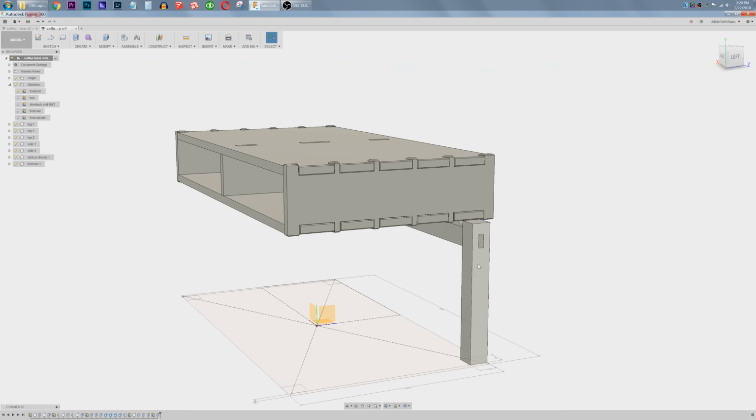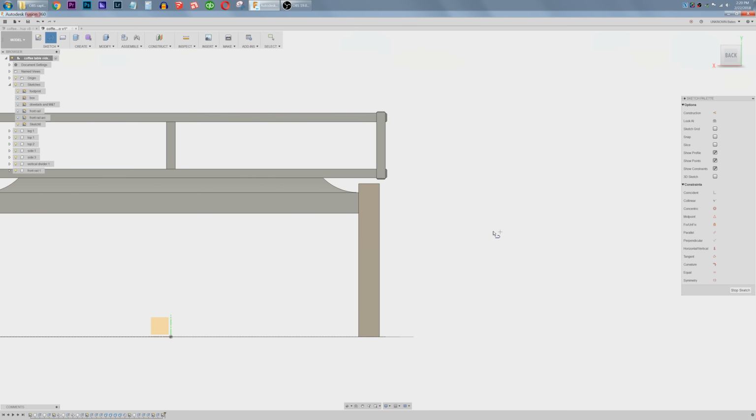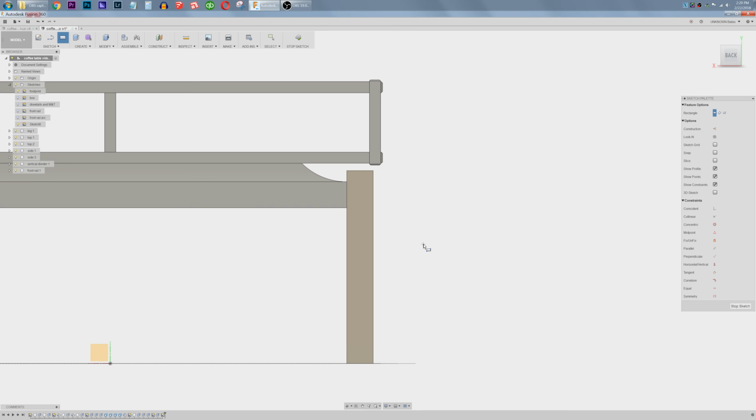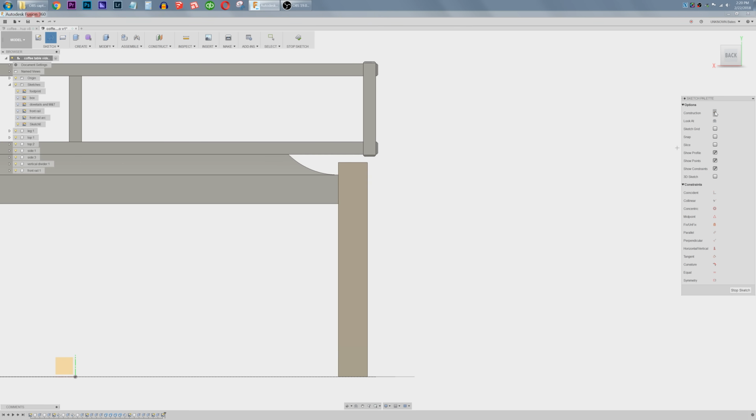This short rail is super easy. I'm going to grab this 6 o'clock to create a new sketch. R for rectangle. Actually, L for line to create a construction line based upon this center point. R for rectangle, and we're going to do a center rectangle. We're actually going to do two of them, one large one. Control Z to back up. I forgot to turn construction off. R for rectangle from the center.